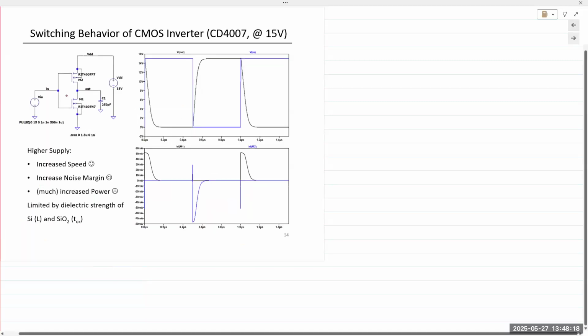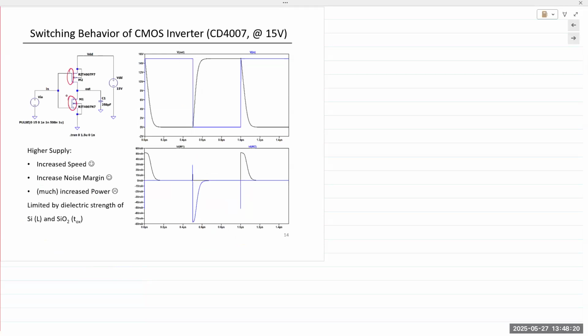So what happens? Well, we have a capacitor at the front end, right? So when you're trying to switch between an on and off state, that capacitor charging and discharging is going to affect the switching speed. Okay. So if you apply a larger voltage, you can increase the speed, plus a larger voltage obviously increases the noise margin.